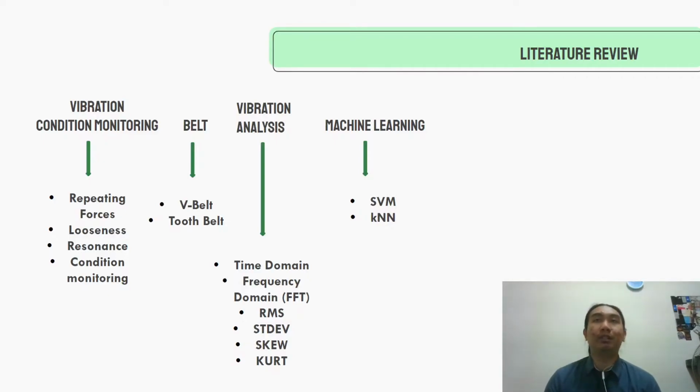Vibration analysis is utilized to decide the working and mechanical state of hardware. Its focal point is that it can distinguish developing issues before the imperfection becomes a genuine condition and causes breakdown. Time domain is time versus acceleration, and frequency domain, which is FFT, is frequency versus amplitude.